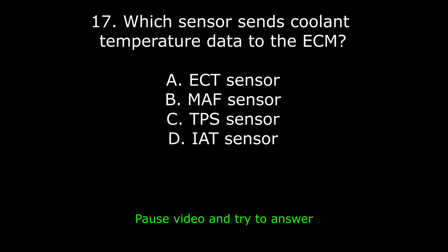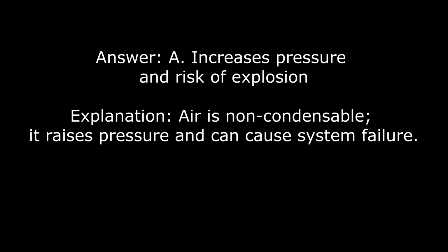42. Why should air not be mixed with refrigerant? A. Increases pressure and risk of explosion. B. Improves cooling. C. Cleans the system. D. Extends oil life. Answer: A. Increases pressure and risk of explosion. Explanation: air is non-condensable. It raises pressure and can cause system failure.